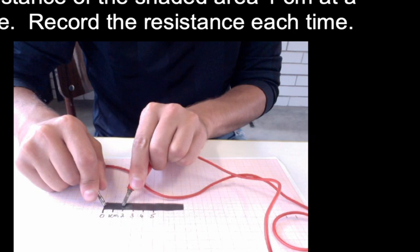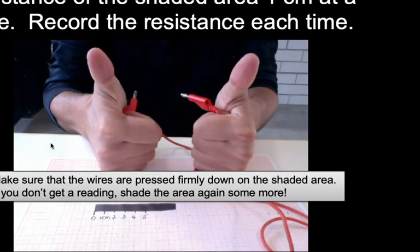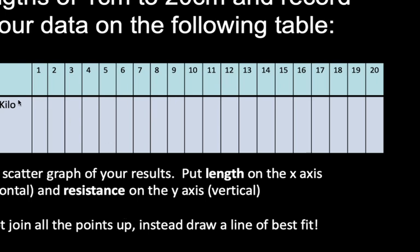So if you actually perform this right at 1 centimeter, 2 centimeter, going up each time, you could get some really good simple quantitative data, make a nice table, and then graph how the length of the strip is related to the resistance, right? So you could even go all the way up to 20 centimeters, plot the scatter graph, right?